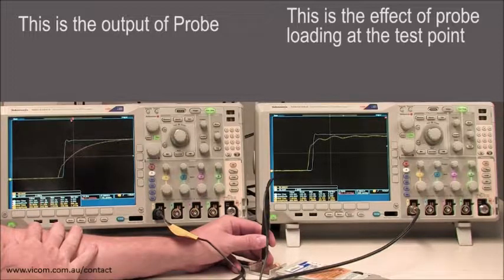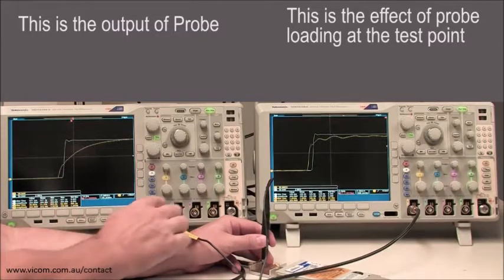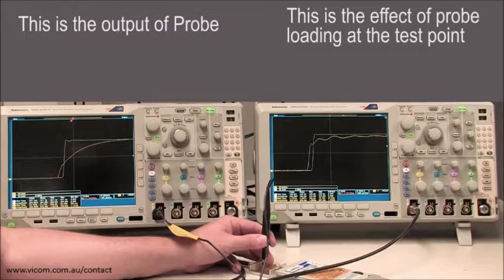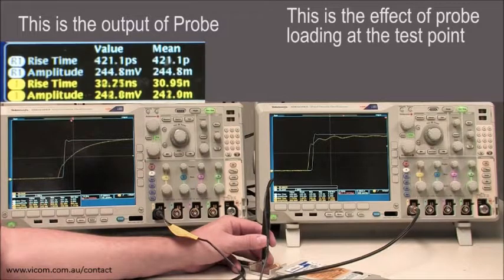This is the signal that is going to travel through the cable to the probe's compensation box and ultimately to the scope. You can see further effects of the probe at the output. The bandwidth is insufficient and the signal was further rolled off and degraded. Clearly, this probe is not capable of making this measurement.